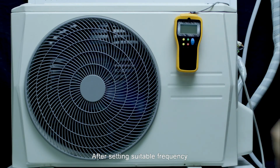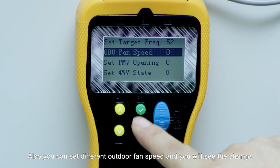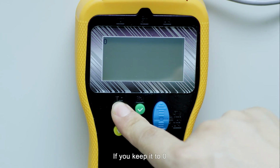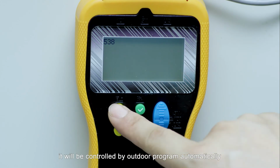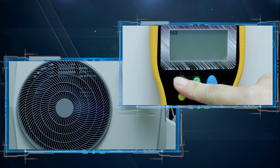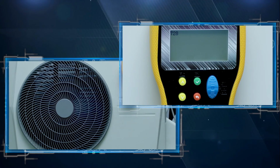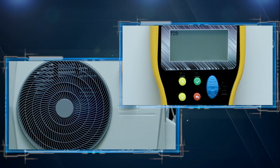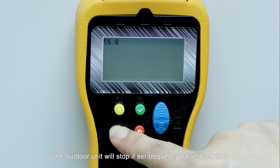After setting suitable frequency, you'll find compressor and outdoor fan will start to run. Also, you can set different outdoor fan speed and you will see the change. If you keep it to 0, it will be controlled by outdoor program automatically. The outdoor unit will stop if set frequency value back to 0.